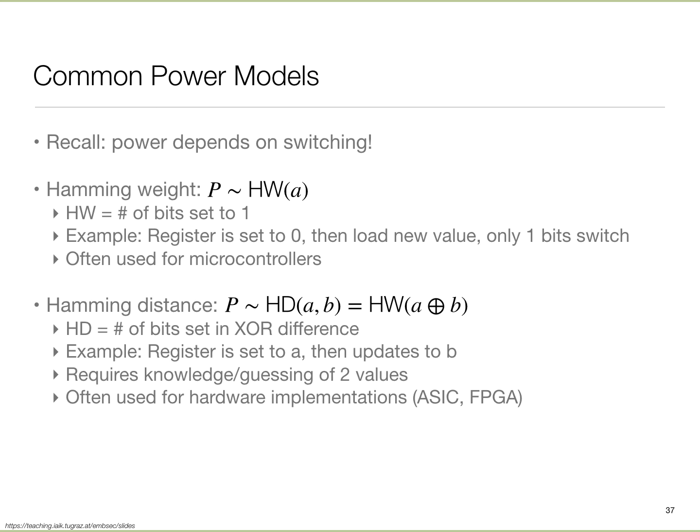Our goal is that I don't want any information about the computation that I am doing, about the secret value, to leak. One thing you are saying is that I do dummy computation. Okay, how would that help? Take the example of AES. We had multiple rounds of computation, and in a naive implementation, the round depends upon whether the key bit was 0 or 1. That's how we are breaking it. So what would this dummy computation look like?